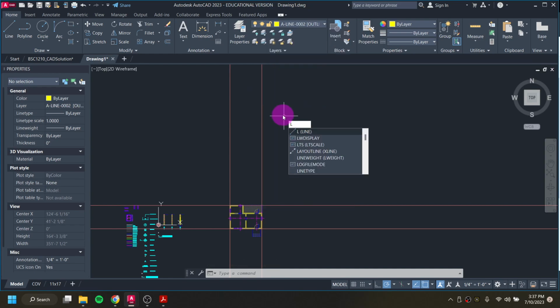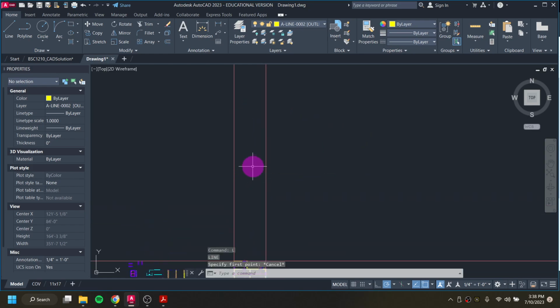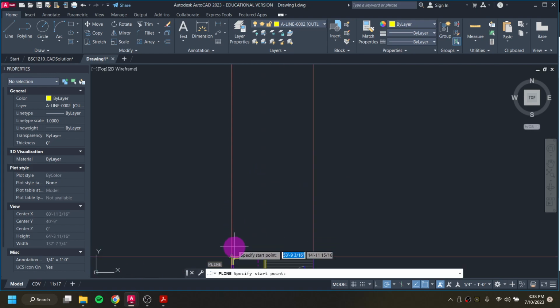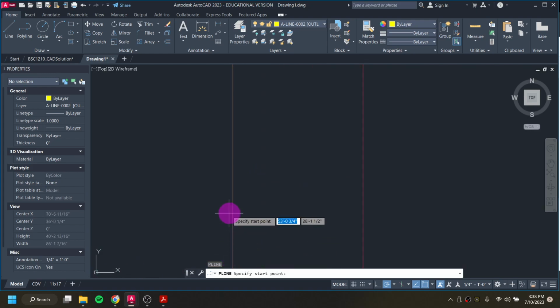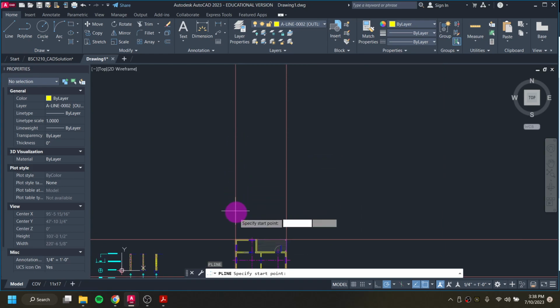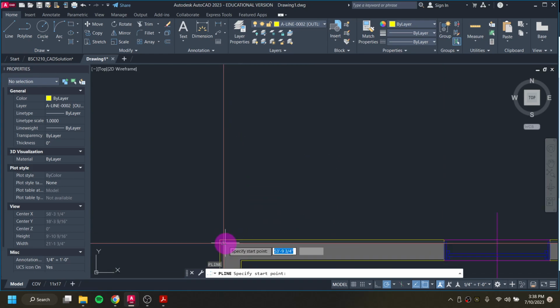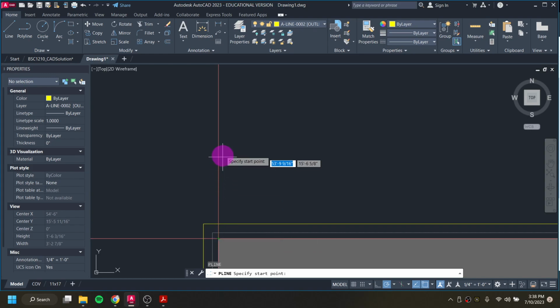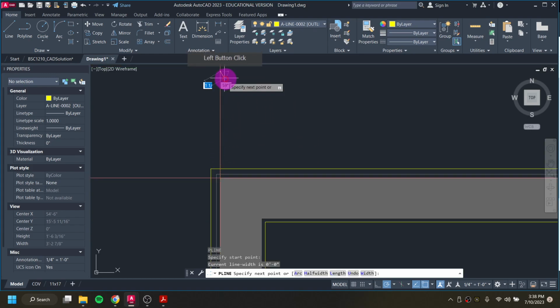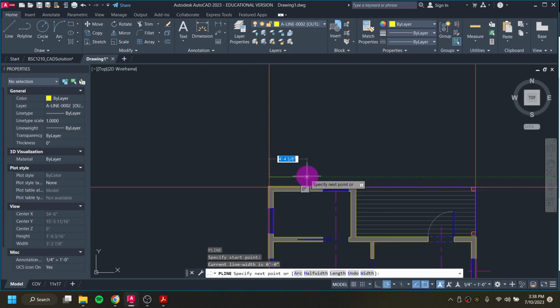And I'm going to draw a line, or rather, let me hit escape. I actually want to do this as a polyline. PL, enter. And I'm just going to hover over my ray here, somewhere where I can get it started, and I'm going to move it afterwards because I'm way too close to the building.